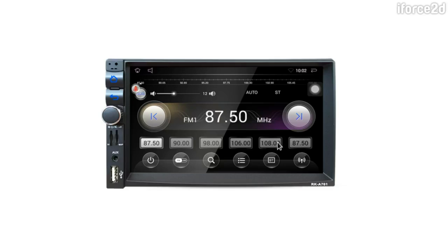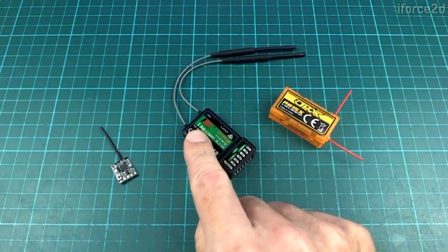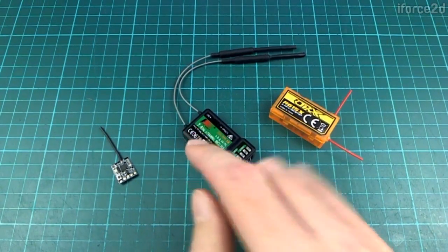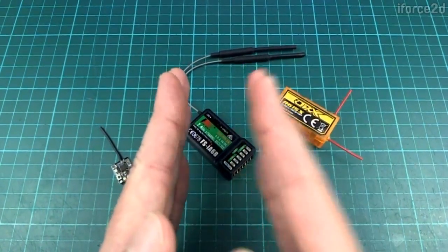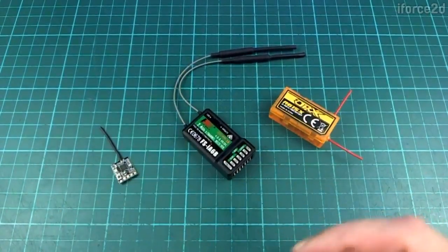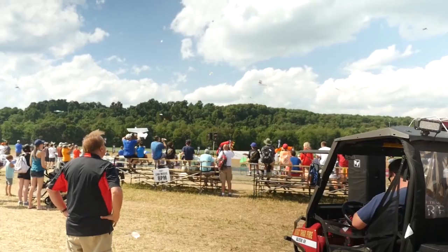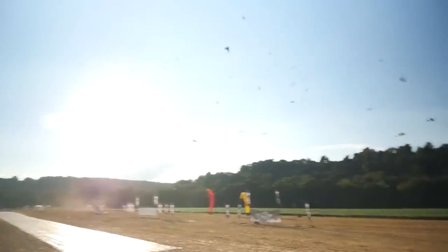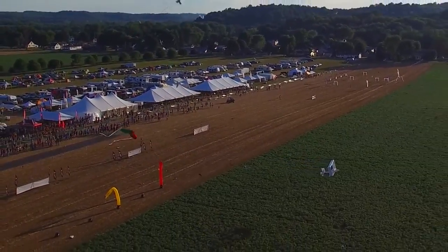So this principle is called frequency hopping, as I just mentioned before, and the radios that we use in these radios here, they do this kind of frequency hopping. So the 2.4 gigahertz refers to the central frequency, or the general range within which that frequency hopping is going on. And this is a really great thing because you can have hundreds and hundreds of people, as we saw at Flight Fest a while ago, all flying lots and lots of radio control planes all together, and they work just fine. It's a great system.